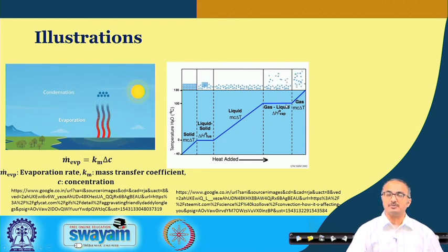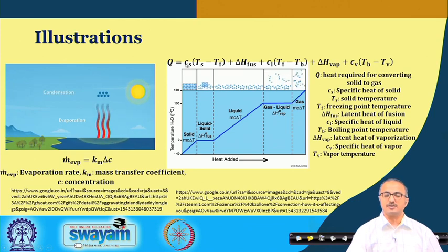And you perhaps also determined how to find out the total amount of heat energy required to convert the state from the solid to the superheated vapor. Okay? So, here you know that this is a solid, subcooled liquid, then saturated liquid, superheated vapor. So, this is a mixture of the gas and liquid you will find, and here we have the mixture of liquid and solid. Okay? So, you are using the latent heat of fusion and latent heat of vaporization, and you perhaps also are aware of this particular equation to find out the total amount of heat required.